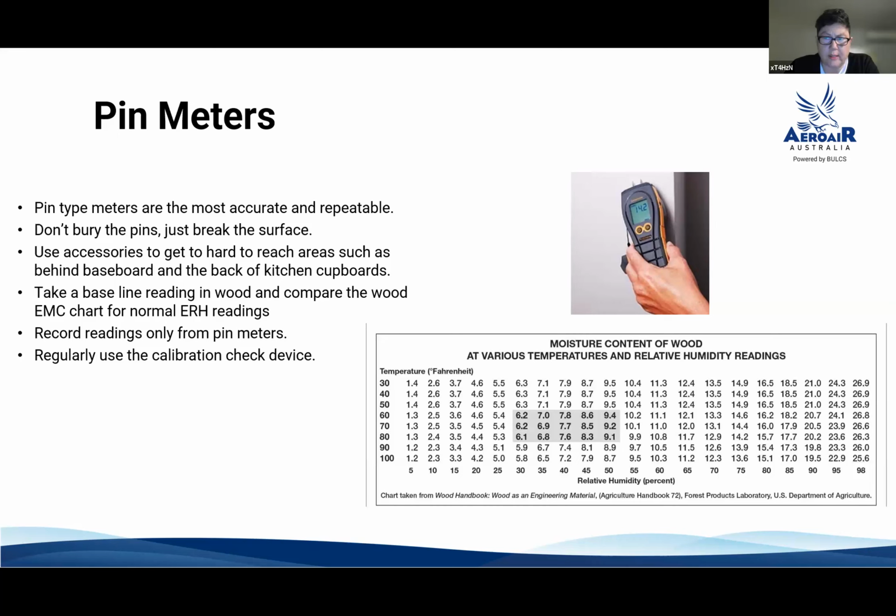But if we're looking at concrete, let's say that we're going to jump from wood and look at concrete. If you have a concrete meter, and let's say I'm going to take a Protimeter now and pin into the concrete, is that possible? You can. It depends, if you talk to someone who has a doctorate, they might say something different, but yeah. I can pin into it, but I would be pinning onto the leveling compound or the screed, and that's not the concrete, and I might even break my meter, so I wouldn't suggest doing that, no.